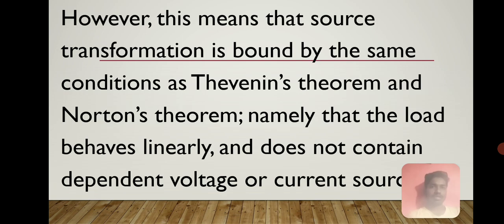However, this means source transformation is bound by the same conditions as Thevenin's theorem and Norton's theorem, namely that the load behaves linearly and does not contain a dependent voltage or current source.